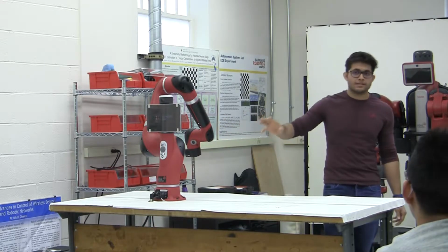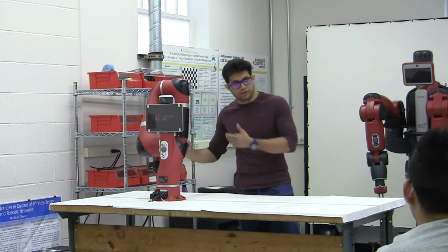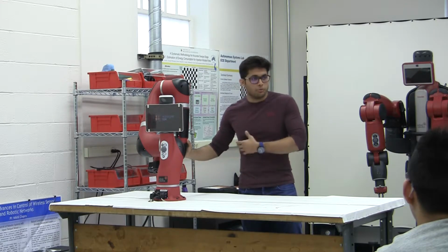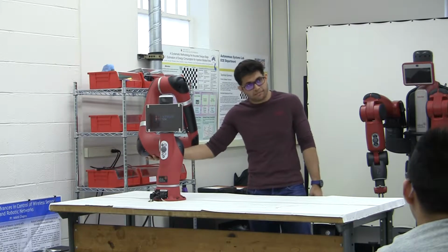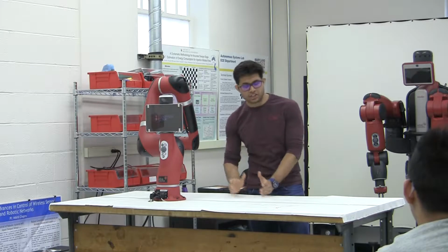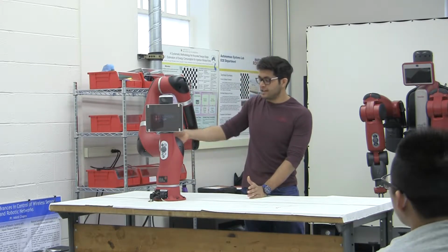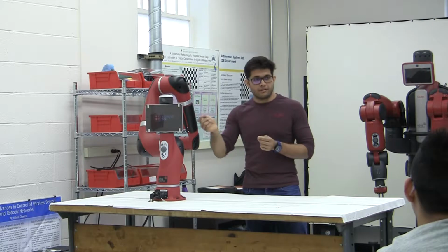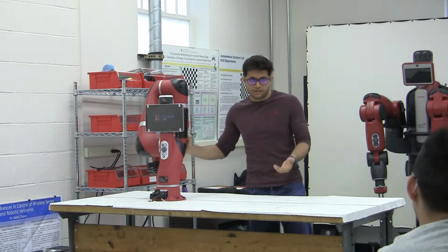You can always define a collision space, which essentially means the robot won't go into that space because it's the collision area. Our joints are still defined with their diameter, but we add an additional tag to that URDF called collision space. It creates an extra, let's say 0.5 millimeter circle around it, or additional space around it, to tell us that's the collision space and we can't go there.